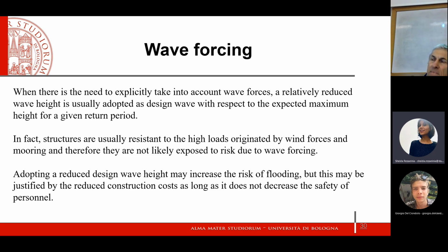Usually, anyway, when we take into account the wave forcing, the wave height that we adopt is usually reduced with respect to the design wave for a given return period. In fact, I told you that the return period that we may take is about 30 years. And it is reduced because it is true that wind forcing may superimpose, may occur at the same time as wave forcing.